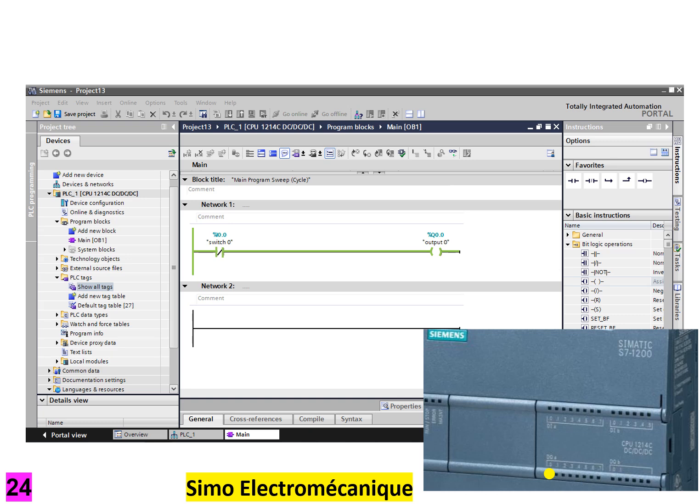If we run this program in monitoring mode with input 0 off, we immediately see that output 0 will activate. This is because the normally closed input is active when the attached switch is off. You can see this by looking at the LEDs on the front panel. Now try toggling the switch on input 0. Input on, output off. Input off, output on.